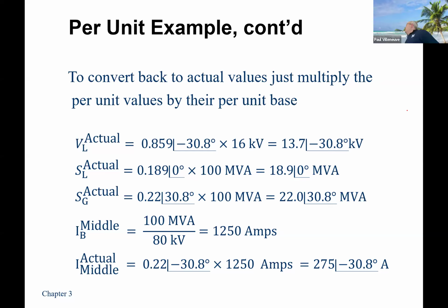So I probably wouldn't convert the voltage. The power, yeah, I'd like to know how many MVA I am, because that's what I get paid on. The generator, I want to know in MVA, because the generator manufacturers, when they sell you a generator, tell you it's a 20 kV generator that operates at, I don't know, 300 MVA. So you can look at how much that is. 0.22 is not that heavily loaded. And since our system operators tell us it's 100 MVA, knowing that that's 0.22 doesn't really give us a lot of very useful information about how hard our machine is getting pushed.